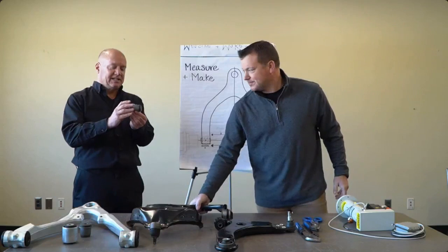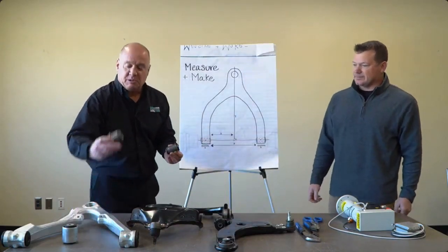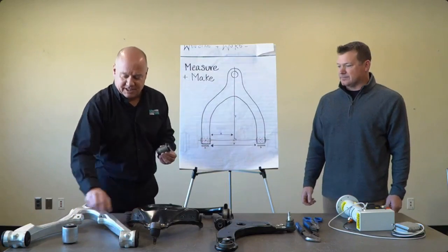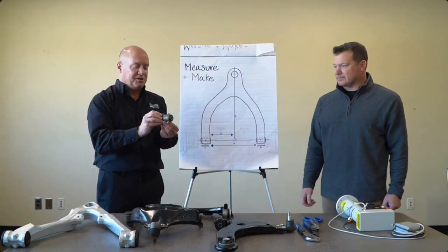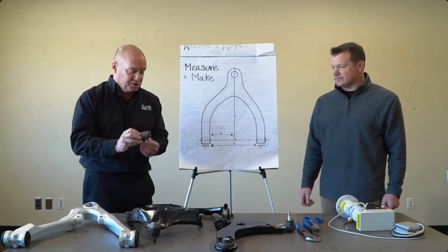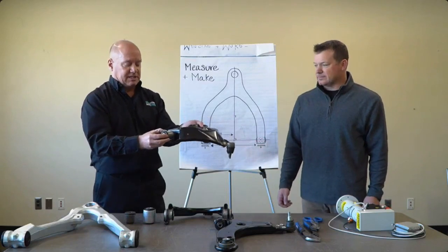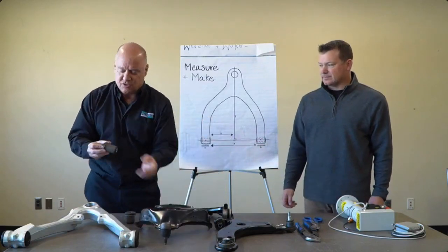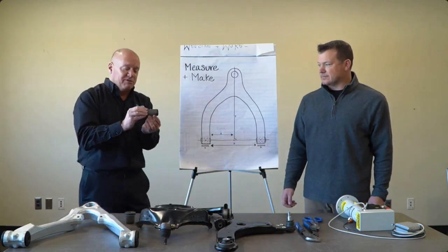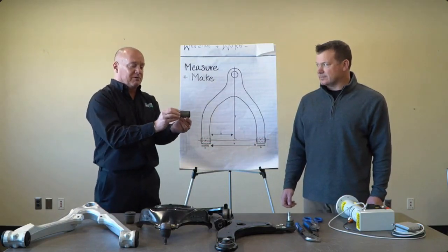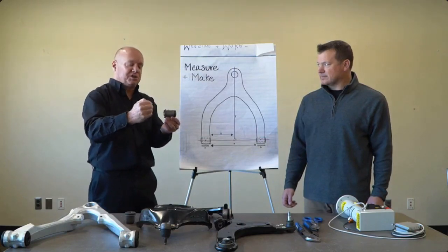And if you look at the bushing, this is a typical bushing. We have a few different models here, a few different types, but they all have the same issue. As I'm pressing this bushing into the control arm, I'm pressing on this outer can. So the press can be perfect and press that outer can to the same place on every single control arm which is manufactured.